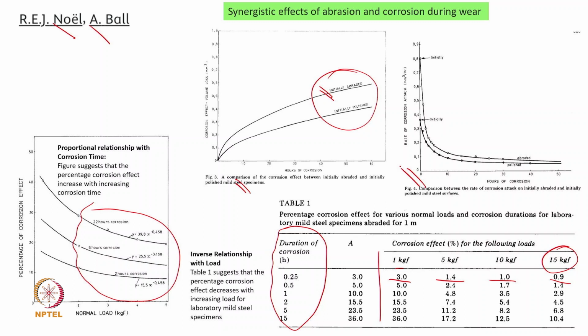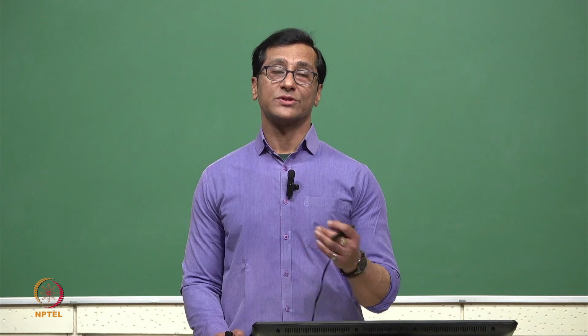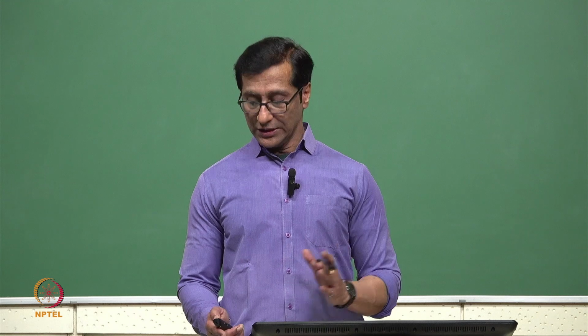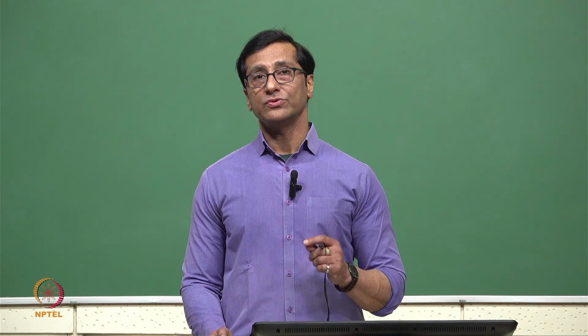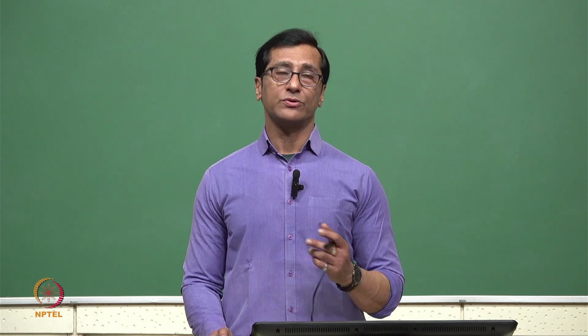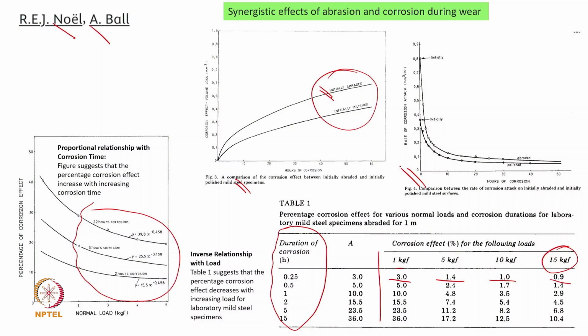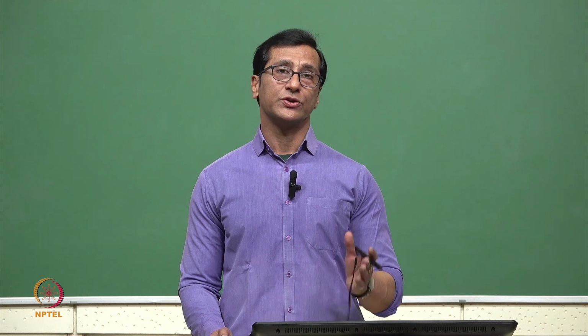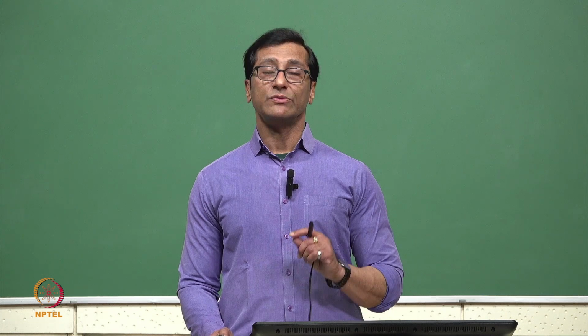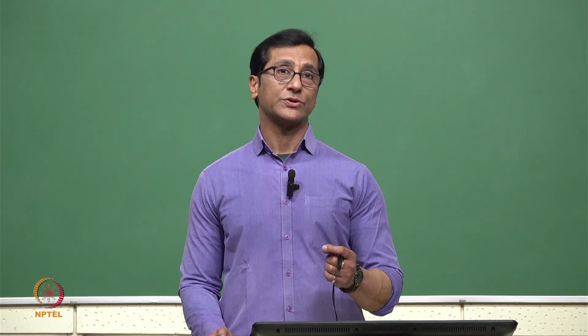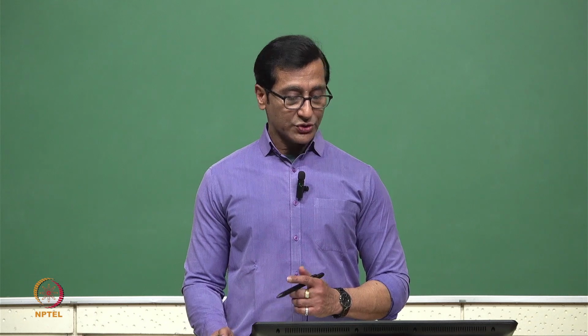So there are a number of parameters: the temperature, load, surface roughness, hardness of the abrasive material, then the kind of shape of the abrasive material. So there are many relations and many parameters, and we need to develop a relation. So when we do experiments in our lab, we need to choose which parameters are very important. We can do some PCA, we can initially assume 10 variables, and after doing initial experiments we can reduce to 3 to 4, and then we can find out the relevant relation, so that we can estimate the life of the component also. This is what the next two slides I'm going to show for this purpose.